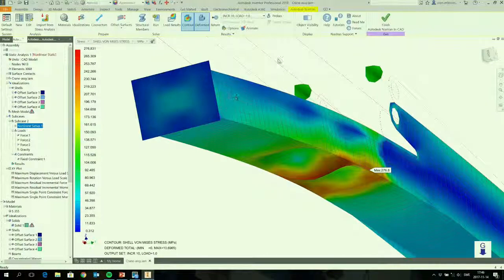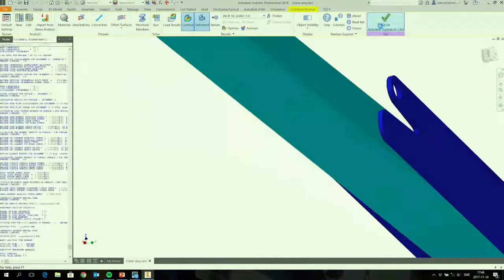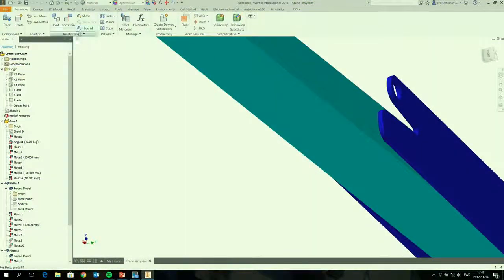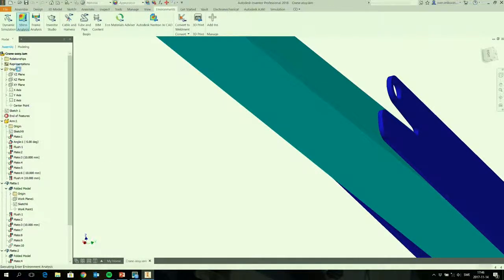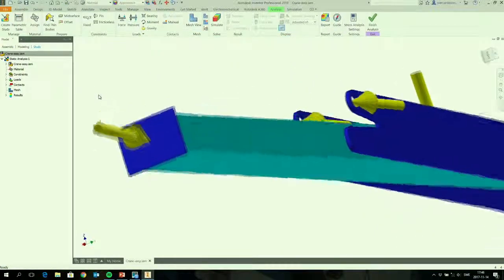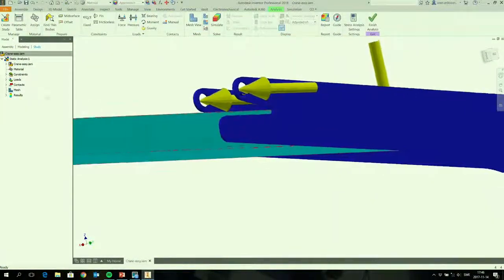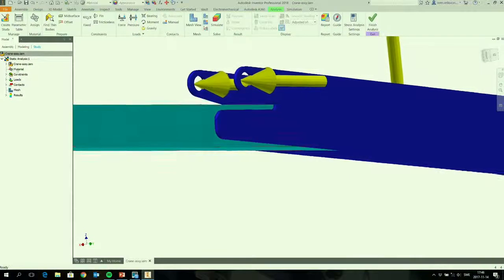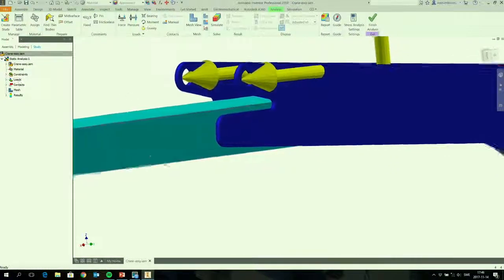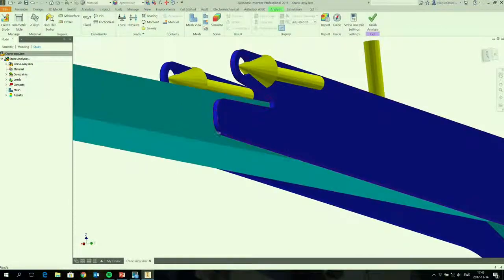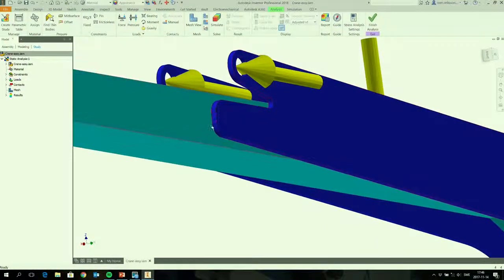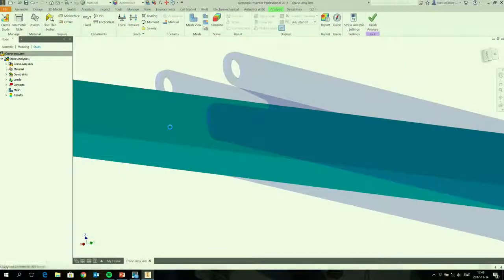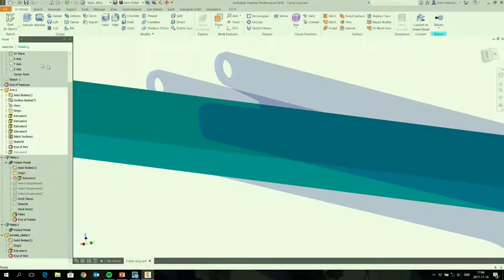This was the last piece of Nastran. I think we can make one more thing also. We go back to the stress analysis. And what I'm going to do is look at the problem here, but adding, let's see, yes, I have everything left. I want to refine in this area where I expect the highest risk of buckling to occur. So what I'm going to do is the standard procedure, I'd say, for this kind of problem. I make a little bit of a refinement here.